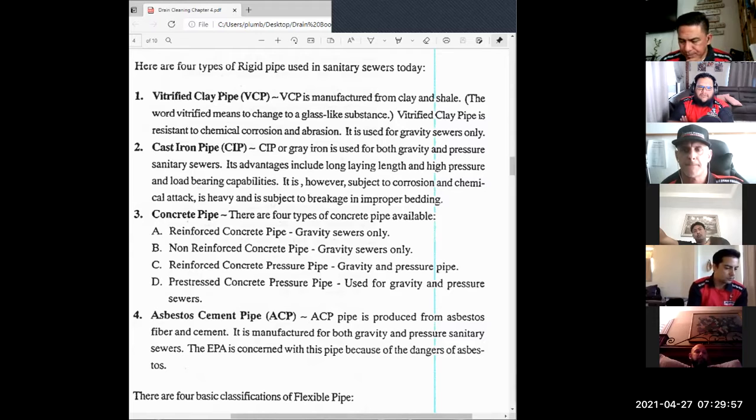Yeah, and I think the concrete before was, I mean, I still see concrete today on rubber gasket fittings because now roots are able to get in, and we see roots all the time at every single joint of a clay pipe. And I think clay pipe comes at a different length. Is it 10-foot lengths on clay? 20? I think it's shorter. It's like 5 and 3 because it's heavy. Yeah.